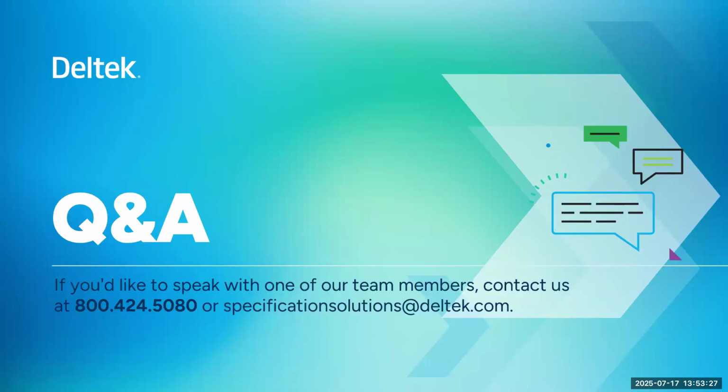That's a really good question. It's a long answer, but let me see if I can shorten it. So when you think of action submittals, these are submittals where they require the design team or project team to review and say basically yay or nay, approved, or that this information is in conformance with the design intent.